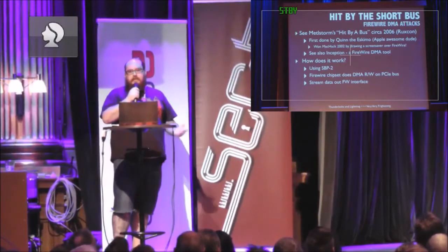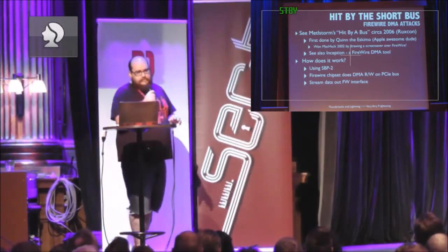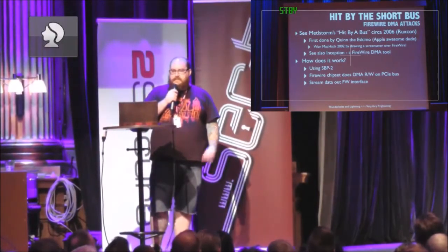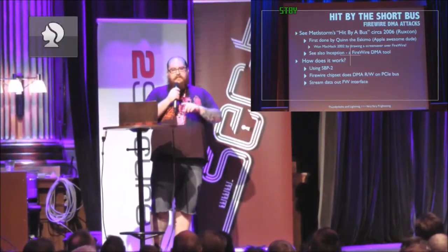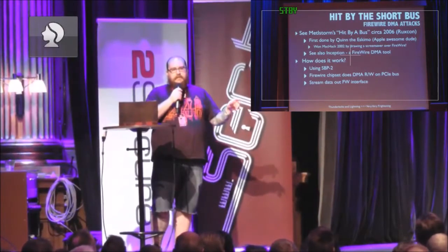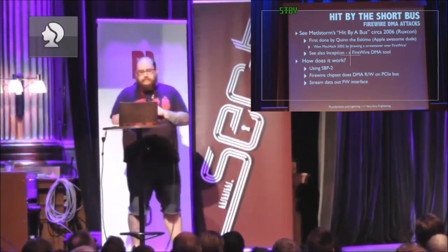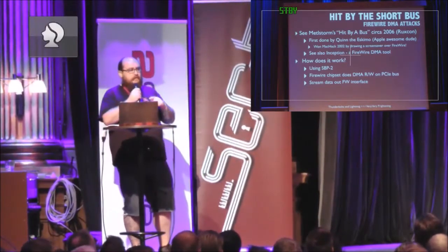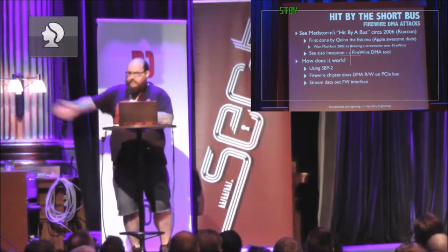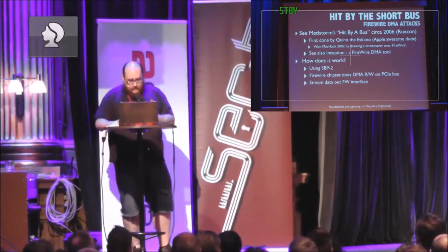Yeah, so basically it works by, there's this sub-protocol or section of the FireWire spec called SBP2, which allows you to send a packet from one FireWire device to another FireWire device that says, please do a DMA read in system memory at this address. Or a write, so we can do sort of PCI Express DMA operations over Thunderbolt and then just spit the data out the Thunderbolt, the FireWire interface. Sorry, I keep saying Thunderbolt and I mean FireWire.